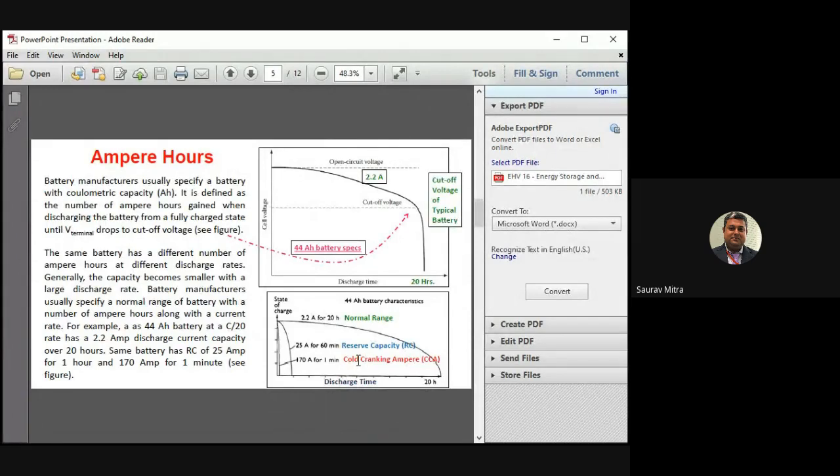That's why whenever they are designing a vehicle or battery for India, where the temperature is on average 15, 16, 18, 20 degrees centigrade, I'm talking about the average temperature of India, at that time battery technology is different. But if they are designing a battery for Canada, where the temperature is always sub-zero and -20, -30 is normal, their battery design has to be different, because there the battery goes into sleep very easily. The lower the ambient temperature, the lower the reaction rate inside the battery, and the lower the energy generation capacity of the battery, and the battery will go bad very easily.